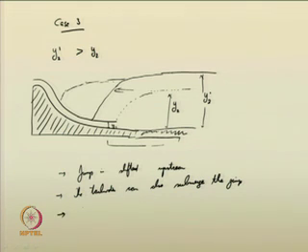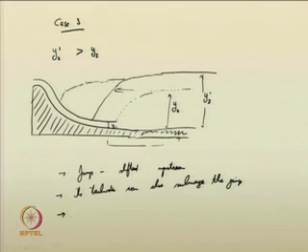For design purposes, one can suggest submerged jumps, because it is not at all creating any havoc. You have proper protective measures everywhere, and for that purpose a submerged jump is also being suggested. But the drawback in submerged jumps is that it is not efficient in dissipating the energy. Whatever energy is coming in, almost similar energy may get transmitted.